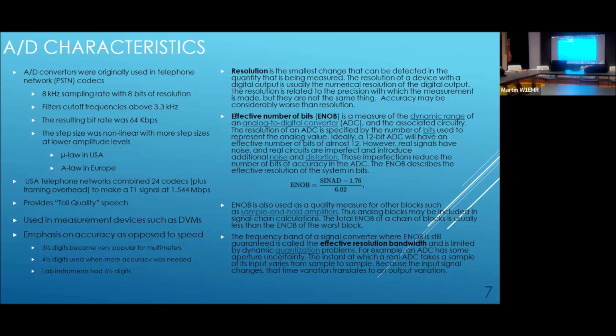Okay. Then if you try to go high, the thing isn't going to measure 15,000 volts, which technically would be the upper end of the range. But guess what? That chip is fried if you come anywhere close to that value. So you could easily exceed the theoretical limits in the practical circuit. All right. So to keep that in mind, we just have the effective number of bits. And we have a simple formula to remember for that.